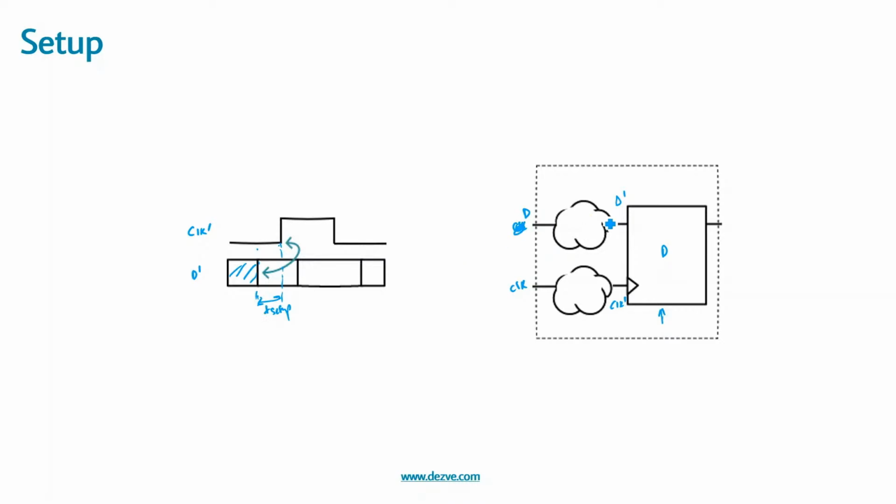Now in this circuit we have added some combinational path. Let us assume that we could have some kind of scan or some other cell, or in a circuit level representation, when we have our D flip-flop instantiated, there can be a clock path delay or a data path delay. Let us assume that this data path delay is T data and this clock path delay is called T clock, correct?